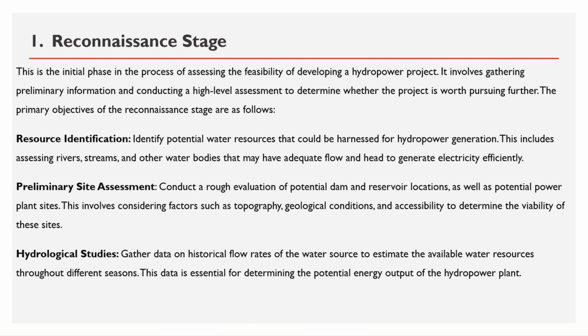Preliminary site assessment. Conduct a rough evaluation of potential dam and reservoir locations, as well as potential power plant sites. This involves considering factors such as topography, geological conditions, and accessibility to determine the viability of these sites.